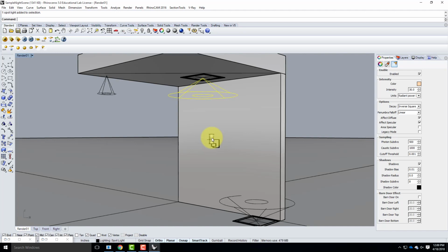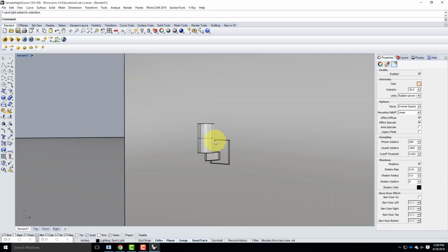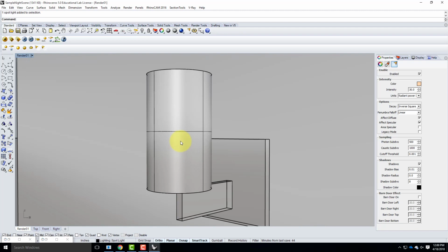Okay? Or 205, sorry. So when you do the spotlight, a point light, you didn't do the emissive material. No, I didn't do the emissive material on this wall sconce because the point light inside was going to shine through it, and that was going to create the glow because I had a shade. If I had a bare light bulb in the room, that would actually be a good one to try to model. You would have the point light shining around everything, but then you'd also have to model the bulb itself, the emissive material of the bulb. So it's a little bit more complicated.